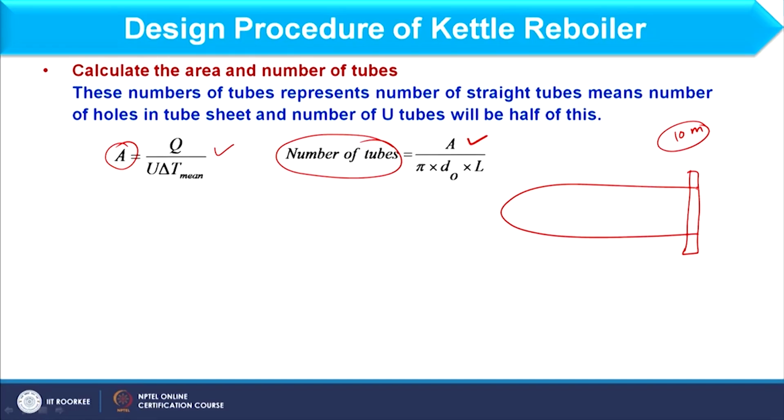That total length enters twice to the tube sheet. Fine. So, if I am considering half of the U tube, it is basically called one leg and it will enter the tube sheet only once. So, L effective you have to find out carefully. If it is the total length of the U tube, you should deduct twice the tube sheet thickness from L to find L effective. Otherwise, it should be deducted only once if one leg of the U tube is given.